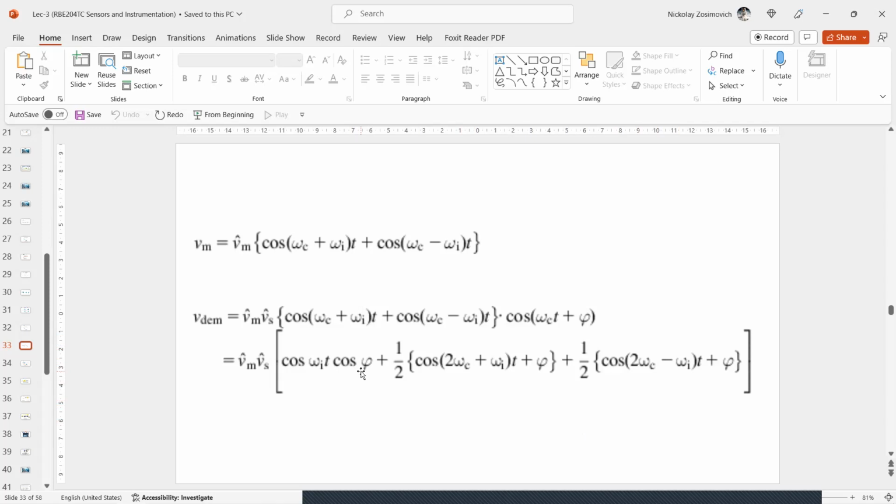And that is when the synchronous signal has the same phase as the carrier. Suppose phi equals pi/2. The demodulated signal in this case is 0, and it has the opposite sign for phi equals pi. And this phase sensitivity is an essential property of synchronous detection.